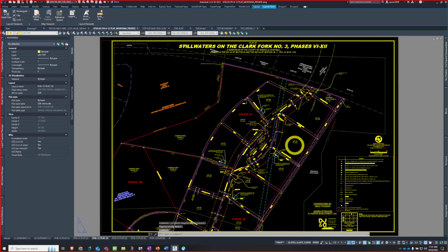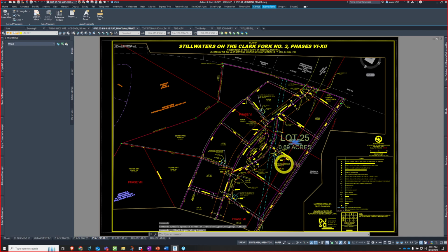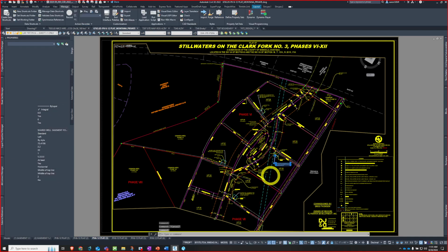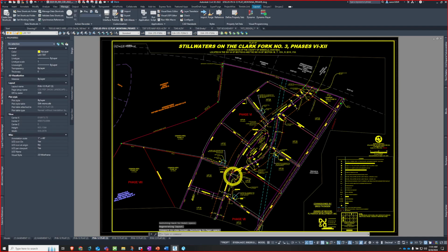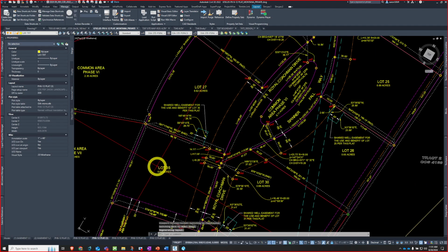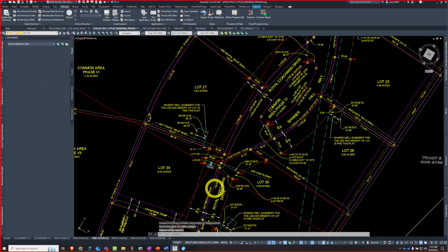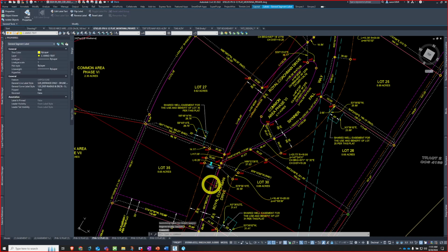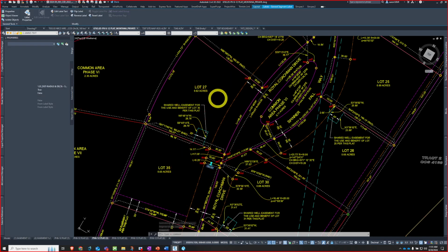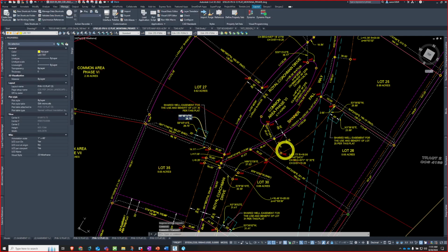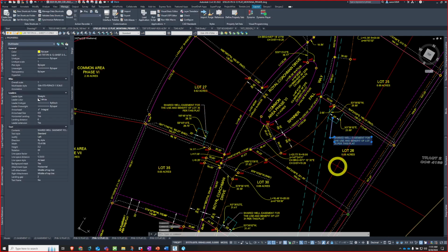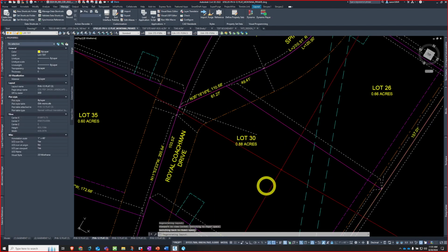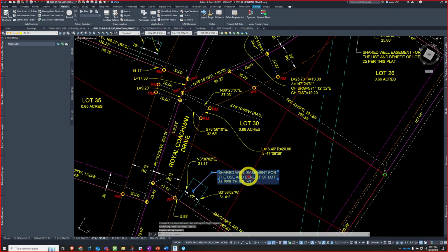And almost everything inside here is annotative: M-text, leaders, and dims. The AutoCAD stuff, like I said, the Civil 3D stuff, those are always annotative. They're just separate worlds. They're always annotative, which is good. Leaders are the trickiest to do annotative. This one I think was not, but I did a few. They don't like to rotate well.